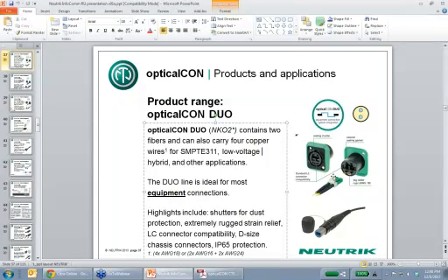This LC connection behind the chassis connector makes sense because this is in a rack. It's immovable. You're going to reconfigure your equipment once in a while, but it's not a patch point. Where you're not patching, use something inexpensive and lightweight like this. But where you are going to do a lot of patching, use something heavy and rugged like this, where you don't have to worry about the connectors ripping off because you don't have a strong strain relief.